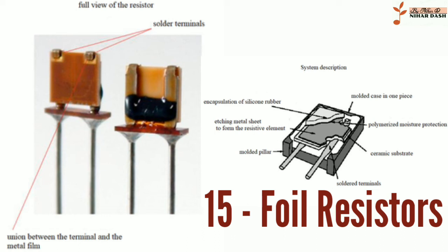Examples are Chromel A and Nichrome V, whose typical composition is 80 Ni, 20 Cr, with a melting point of 1420 degrees centigrade. When iron is added, the chromium nickel alloy becomes more ductile. Nichrome and Chromel C are examples of alloys containing iron. The typical composition of Nichrome is 60 Ni, 12 Cr, 26 Fe, 2 Mn, and Chromel C, 64 Ni, 11 Cr, 25 Fe. The melting temperatures of these alloys are 1350 degrees and 1390 degrees centigrade, respectively.